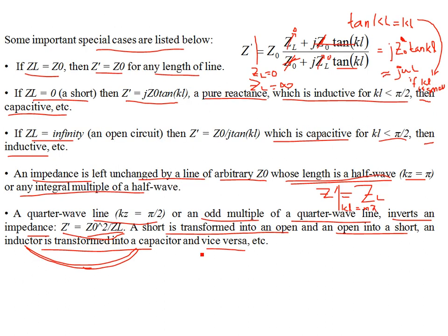Okay. What we have considered so far is a transmission line that is lossless. A lossless transmission line does not have any dielectric loss, and you're not considering the resistance, which is the finite resistivity of the metal wire conductors. This is in terms of the distributed inductance and capacitance per unit length quantities. So Z0 is the square root of L over C for a lossless transmission line. This case is for a lossless transmission line. What if the transmission line is lossy?